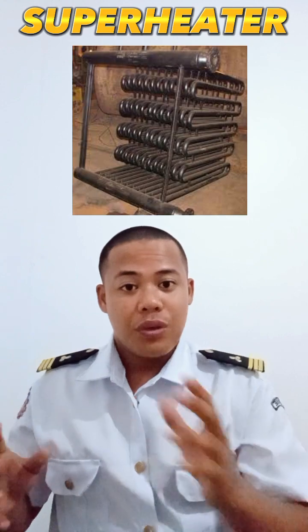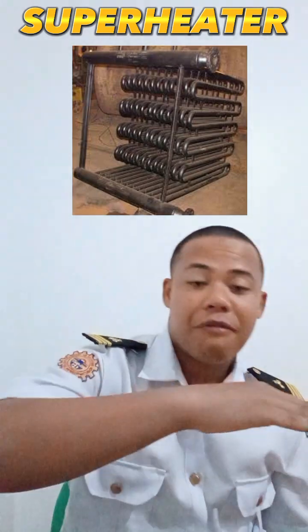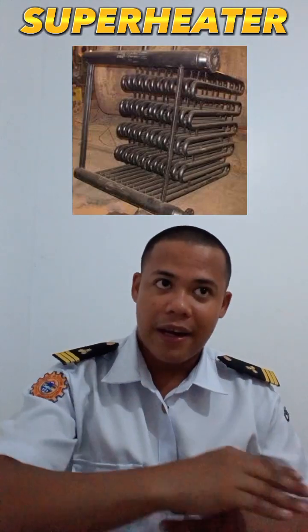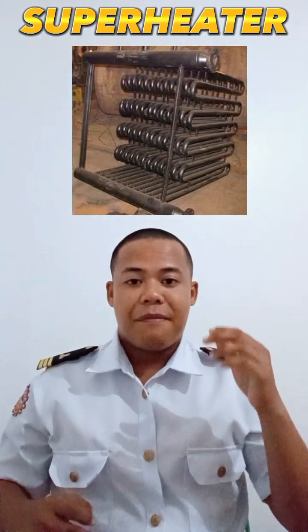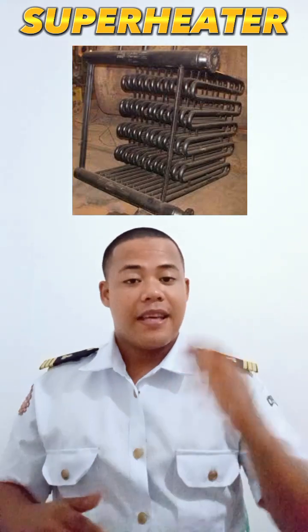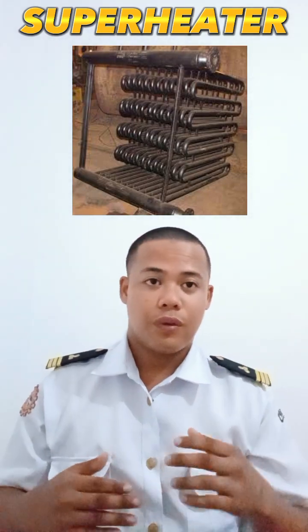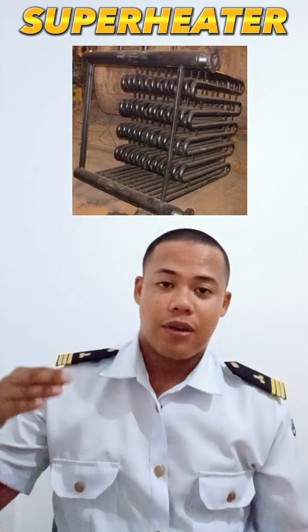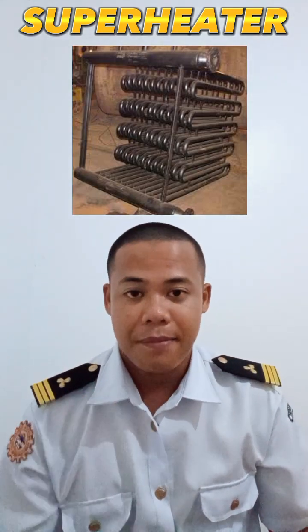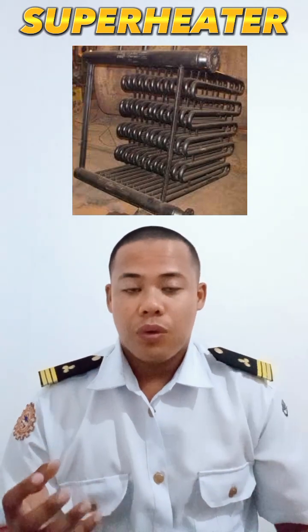It allows the saturated steam to flow through the superheater. So this saturated steam flows through the superheater before leaving the boiler, to improve the energy content of our steam, and hence the steam plant thermal efficiency, since we allow the increase of, or no vapor at all in our steam, because we turn it into superheated steam. So we turn the steam into dry steam.